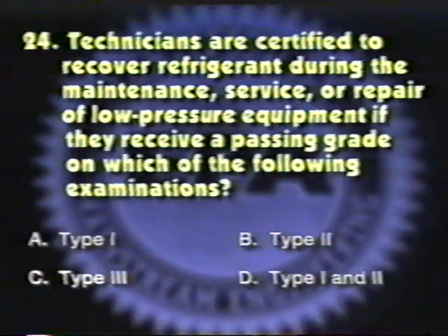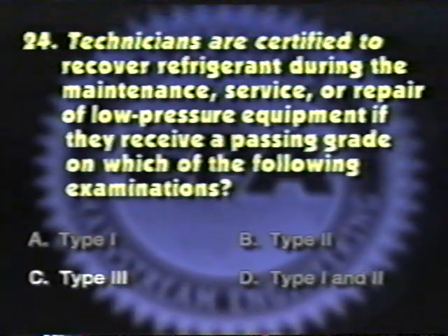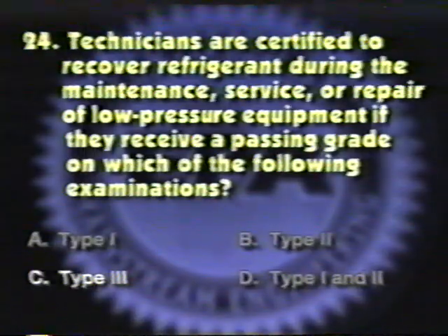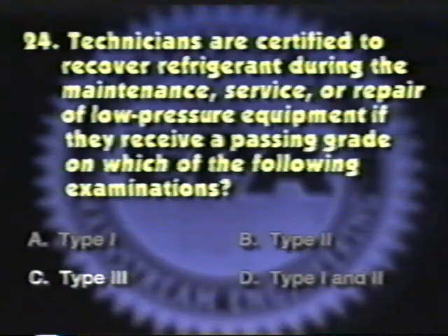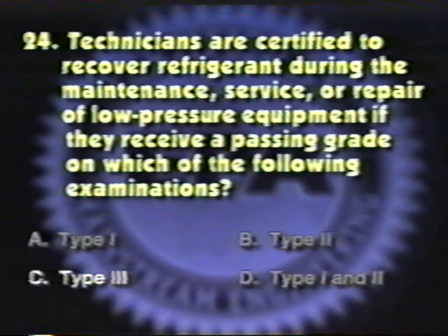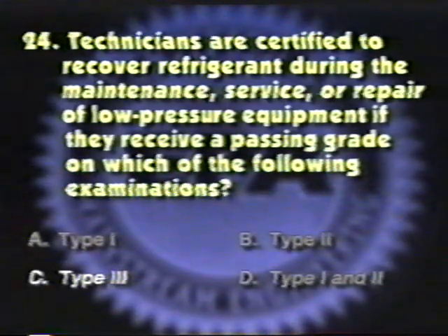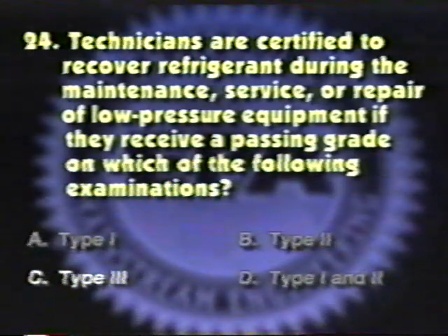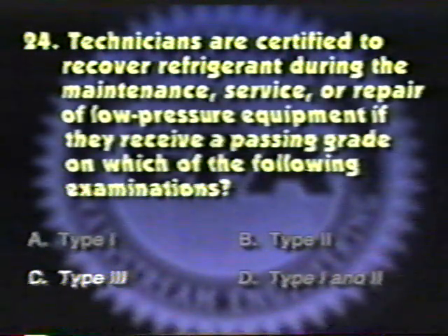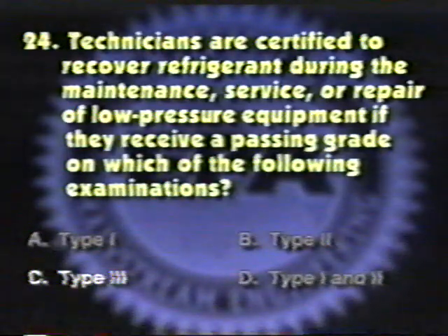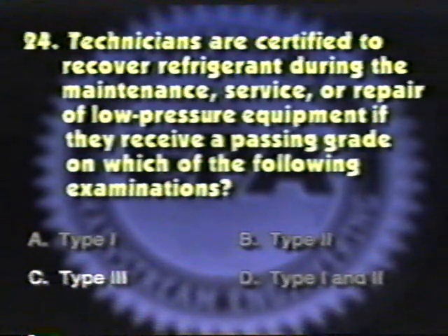The correct answer is C. Technicians receiving Type 3 low-pressure certification can recover refrigerant during the maintenance, service, or repair of low-pressure equipment, such as CFC 11 and HCFC 123 equipment. Only Type 3 or Universal Certified Technicians can recover refrigerant from these units. Be sure to know which refrigerants are considered low-pressure refrigerants.